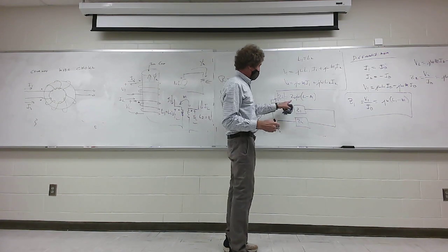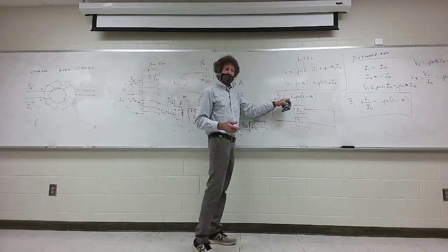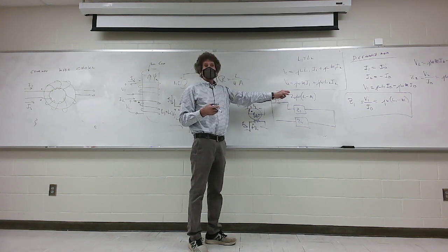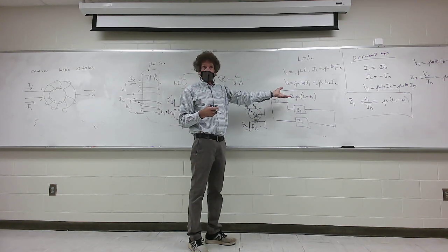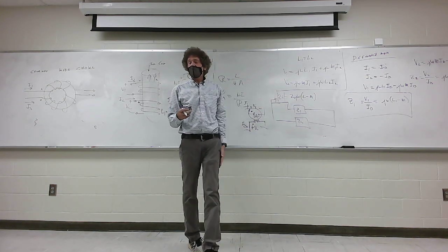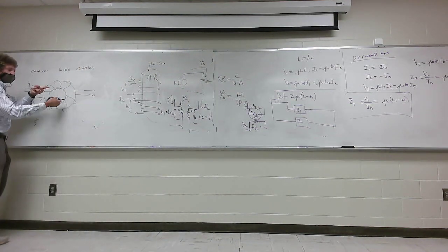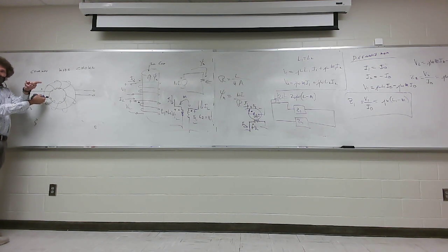Now, if you look at this, y'all agree with that, first of all? What's the one thing you notice about the self-impedance if L is equal to M? What happens? It's 0, right? And the whole idea is when you have a common mode choke, you don't want this thing to interfere with any normal communication, power or information, and it won't.